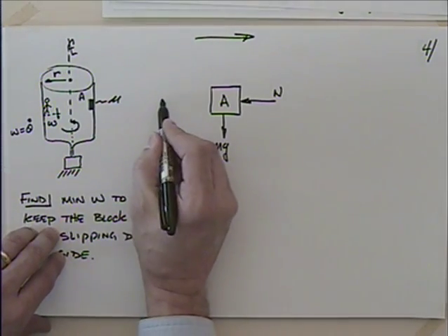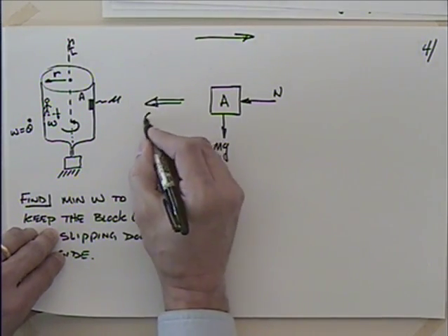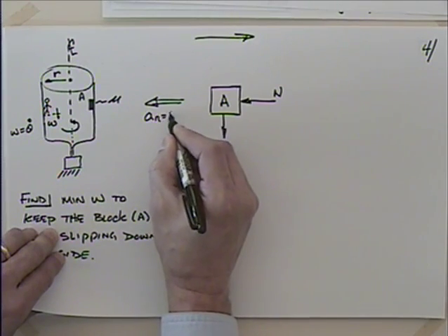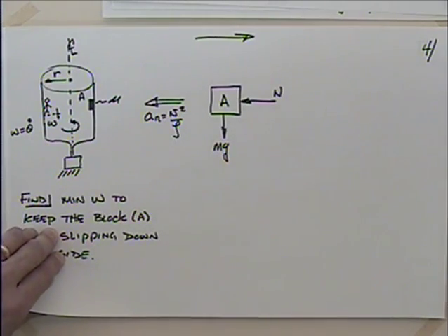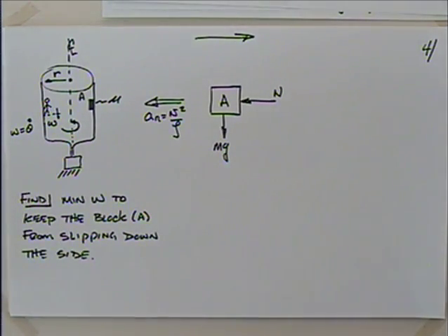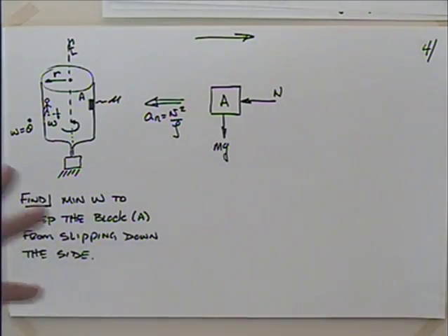What about an acceleration? Are you going to have an acceleration? Absolutely, you have an acceleration in the normal direction that's equal to v squared divided by rho, the radius of curvature, right? You could call this the centripetal acceleration, and you know the acceleration is on the opposite side of the equation in Newton's law, so if you wanted to, you could come back and put this force going the other way. That's what they come up with, that fictitious force, the centrifugal force, right? That's really wrong. They should call it centripetal acceleration.